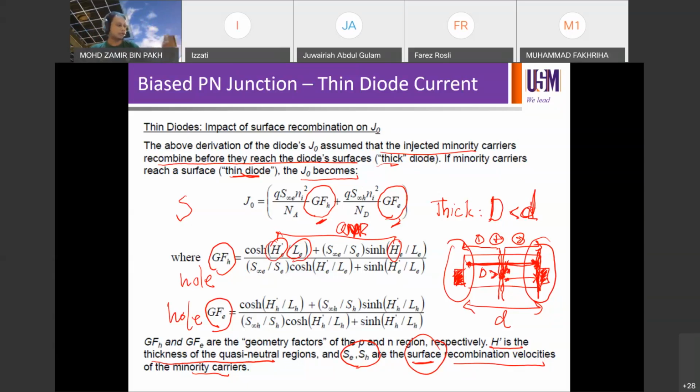On the other hand, if you are talking about the thin diode, we are referring to the solar cell as well, but the one that we have in our calculator. Sometimes you have a calculator with a thin, amorphous solar cell, you see? Or if you look at smartwatches now, some have solar cells embedded in the watch. We have other gadgets with solar cells, or a charger to charge your phone, which use thin film solar cells with a device thickness of less than 1 micron, compared to wafers which use 200 micron.